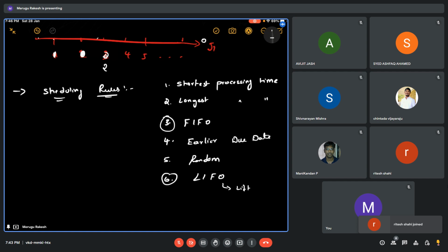Then the other thing is shortest processing time. These are very important for GATE. One is the shortest processing time, and the other one is the earliest due date. So there are questions on these two models, and I'll come to them one by one. The principle remains the same. Previously, we followed an empirical method of taking the least possible processing time and sequencing the jobs.